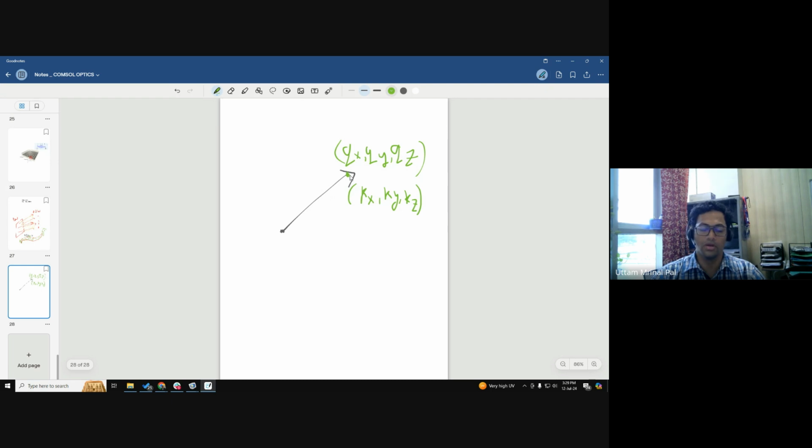Now assume that you want to model around 1000 rays. You just need to multiply by 6, so it's actually 6000 degrees of freedom directly from the rays. There would also be some degrees of freedom coming from the geometry. The good part with geometric optics is that if there is a big domain, you don't need to mesh the domain.